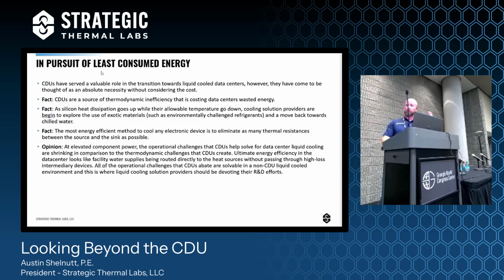CDUs, on the other hand, tend to operate at half of that or less, right? So cold plates are being designed for CDU water networks that have maximum static pressures of 50 psi, as an example. If you make a cold plate for a processor that's meant to survive facility water supply, it means designing a cold plate that can survive 150 or 200 psi pressure. That's not difficult to do if you design it that way from the beginning. Just talk to some of the folks who are doing two-phase refrigerant-based cooling. All the refrigerants being utilized for that are high-pressure refrigerants. It's quite solvable.